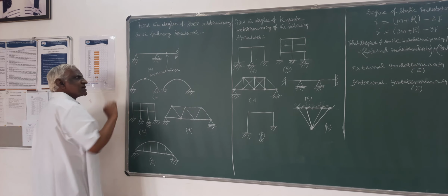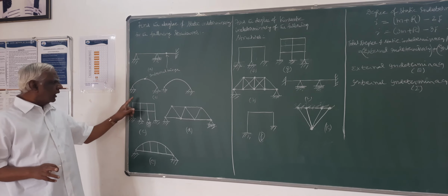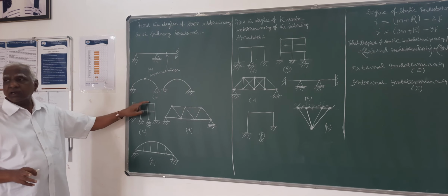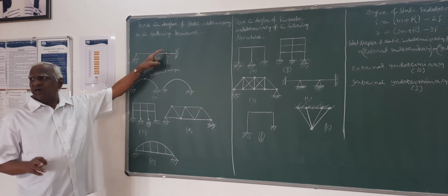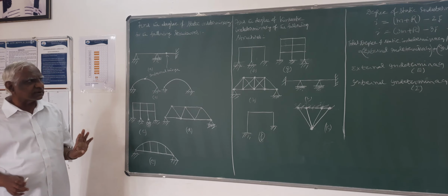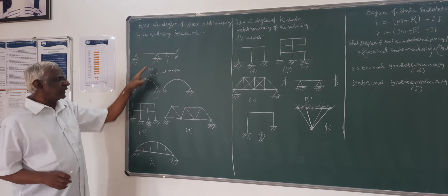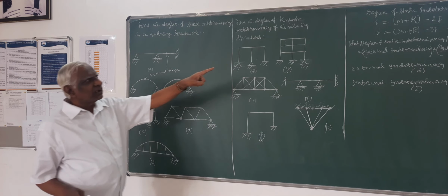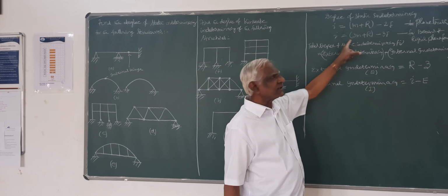It is not a support or a continuous joint. Here, all these joints are called continuous joints. Here, it is not a continuous joint, it is just a hinge in the one member itself. That's another thing you have to remember in the assembly of structures. Whenever you have that type of arrangement in a structure, you have to slightly modify these equations.